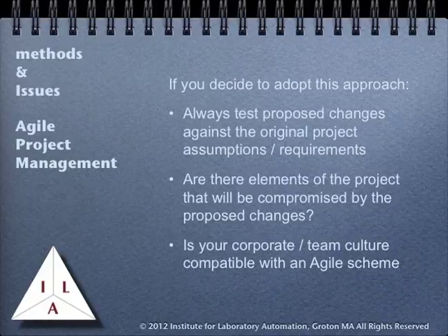Always test proposed changes against the original project assumptions or requirements. If a change is requested, you have to be very careful that some critical fundamental element isn't compromised. If the system is structured properly, things such as changes in equipment models within a product family may not matter very much, but substituting one vendor's data management system for another could easily knock the project back to square one.